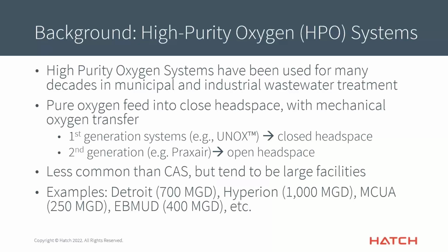So I'll show you an example of a project that we did with Praxair where they had a sort of aerator mixer situation where they would be able to feed the gas down in and trap all those bubbles under the surface. So certainly these HPO systems are less common than traditional conventional activated sludge, but they often tend to be fairly large facilities, and there's a few examples of quite large plants that are using HPO.